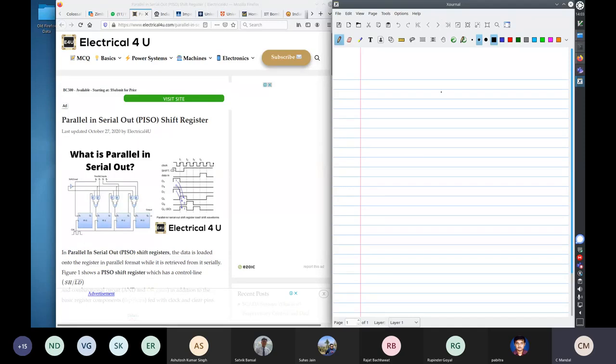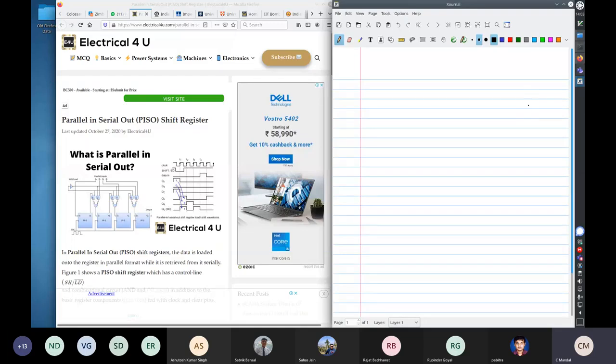So you are familiar with D flip-flops, right? A shift register is just a chain of flip-flops. For the double, the data moves from left to right, so I am drawing it accordingly. You can draw as many as you want. So these are all D flip-flops.